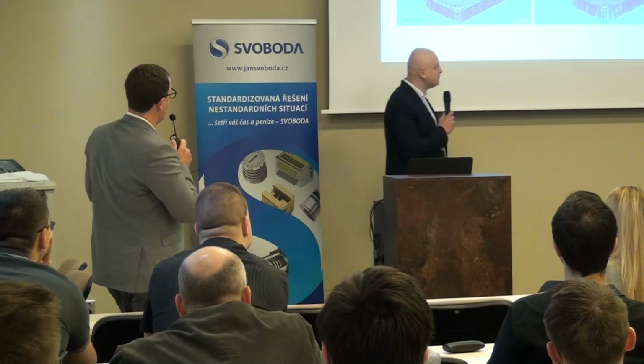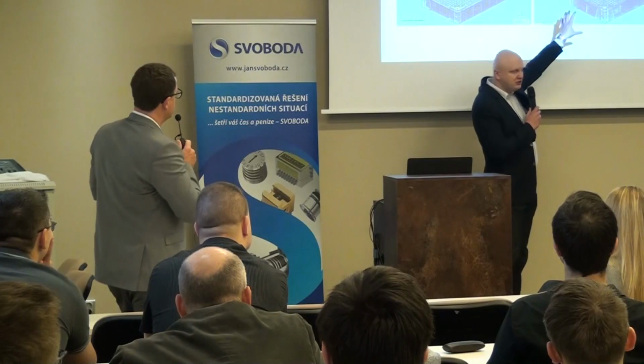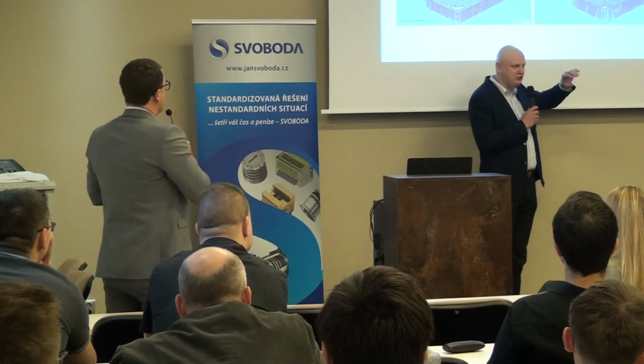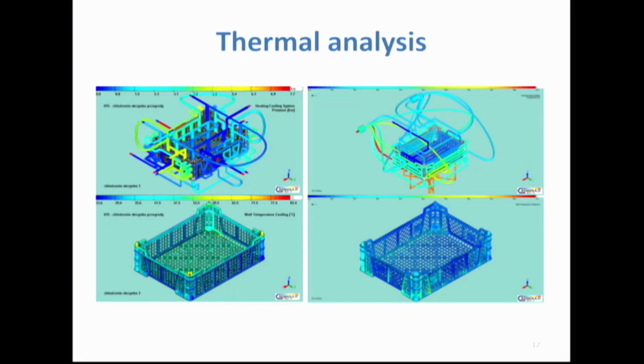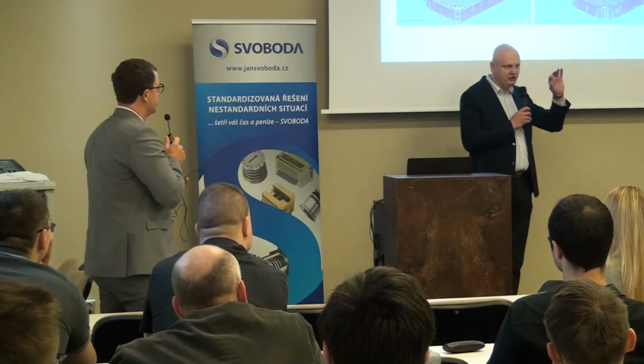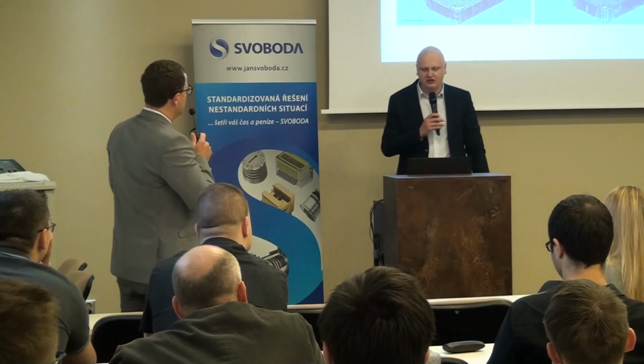So our idea was to redesign the cooling system to be much simpler to machine in the tool shop, but much more effective. Actually, this cooling system is something like conformal cooling, but it's done in the normal way. We just make a drill, not using any special techniques.